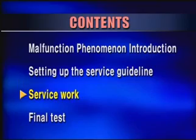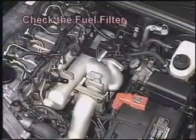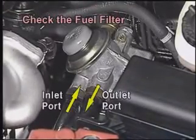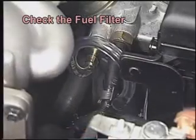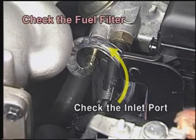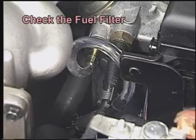Service work. Check the fault on the fuel filter. As shown on the screen, the filter is placed under the intake manifold. Here, the most important thing is checking the fuel flow amount at the inlet and outlet port. As shown in the picture below, it is recommended to use a transparent tube. You can see that the fuel is injected from the fuel tank to the common rail pipe. This picture is for normal operations.